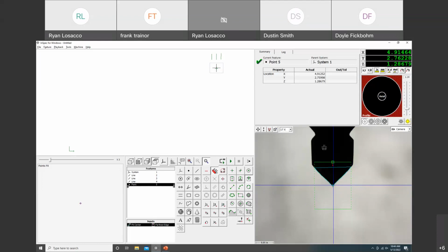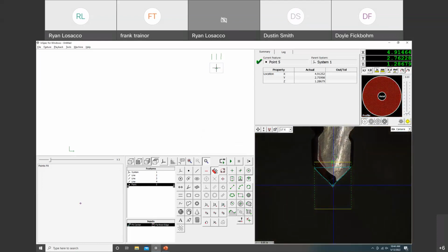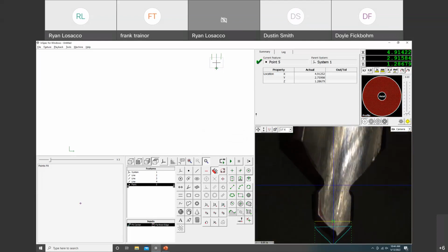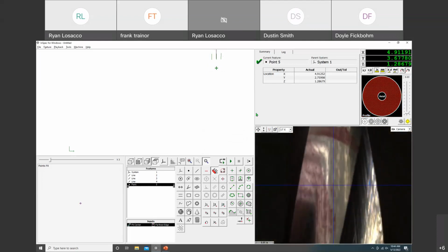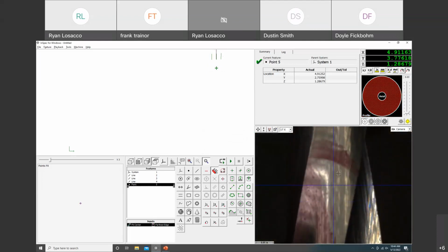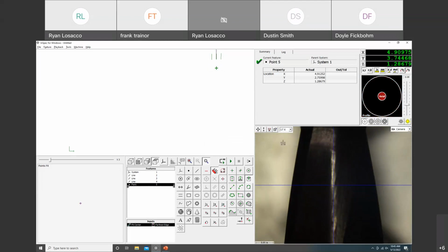So now I do, that's kind of a turned surface. So that actually, I might not want to use that as my Z. I'm going to come up to find where I can see kind of the apex of the turn. And a little trick is if I use axial light, that axial light will show me right where the top part of my turned part is. So this is really good for any turned parts that you have going on here.